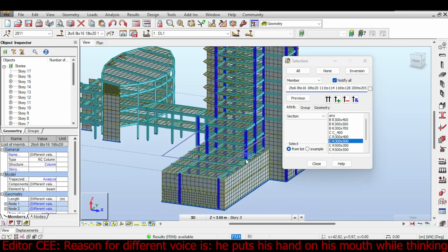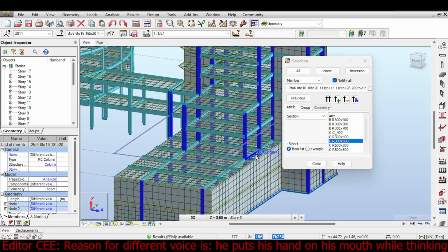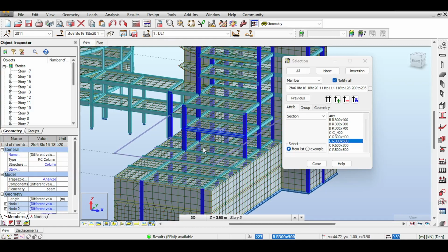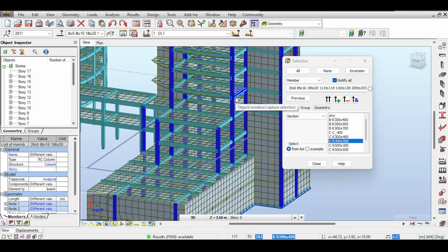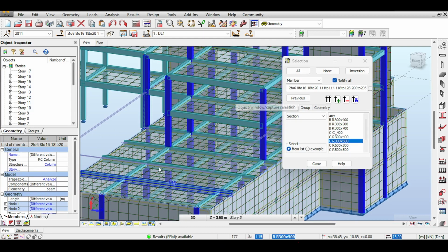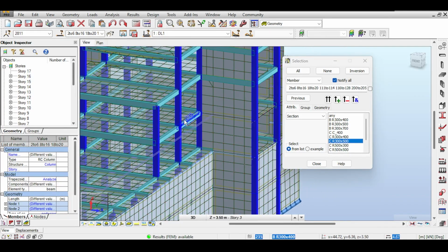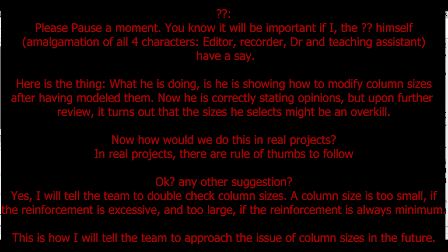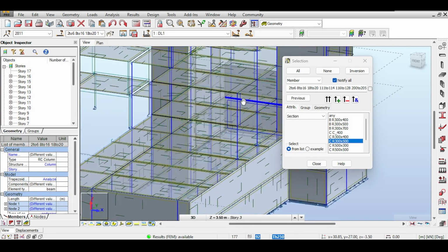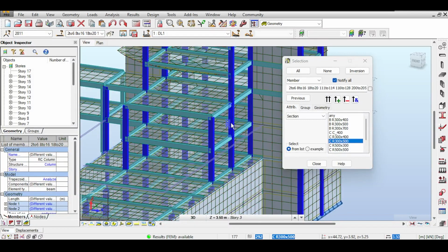In the bottom, I will have it to be. Now, the problem is that there are 2 bottoms, right? There is a bottom below the car park and there is a bottom below the structure. Oh my, that's gonna be interesting. So for those, 300 by 500 is okay. For those, maybe I think 3 slabs are okay, or 4 slabs. But those, absolutely no. Those are too weak. And those columns might be okay-ish up to the slab, but those columns are weak.